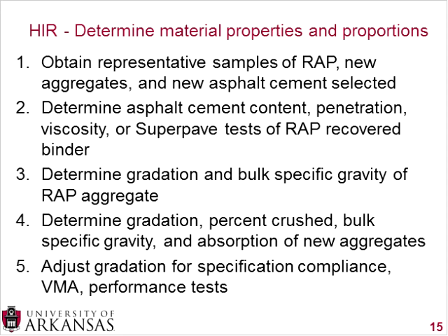So you do want to try and simulate the gradation as best as possible. You also want to figure out your bulk specific gravity, and your percent crushed aggregate with that RAP. If you're doing some milling, you might be doing some crushing, but you want to know what you have in place, and also the absorption. And this goes for all of the existing in-place material and also any new aggregates that you bring into place.